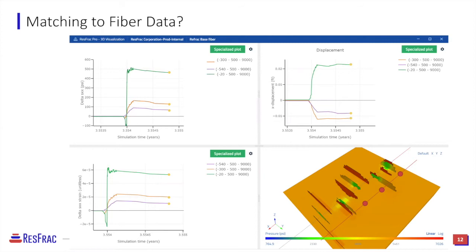Yeah, I was just trying to get at whether or not it's using the matrix properties or the 1D submesh method. Oh, yeah. So the 1D submesh method is used for fluid flow, like the leak off in production. The stress shadowing from the fracture's opening is done in a different way completely. It uses the displacement discontinuity method. The way that works is you mesh only the fractures, and so the matrix mesh that you construct has no effect on the stress shadow calculations for crack opening. The mesh that's used to calculate the stress shadow for crack opening is the fracture mesh only, and it doesn't need the matrix mesh to do the calculation.